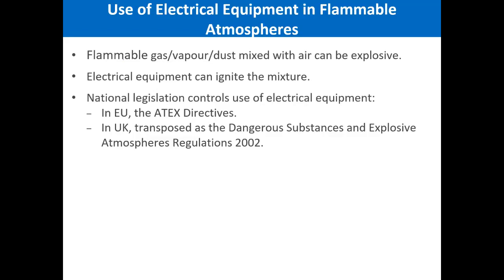So if, for example, H2S is a flammable and combustible gas, the lower explosive limit is 4%, upper explosive limit is 40%. So if there is less than 4% H2S in the air, even if you ignite it, there will be no fire, there will be no explosion.